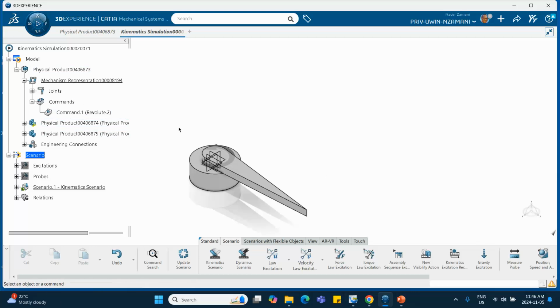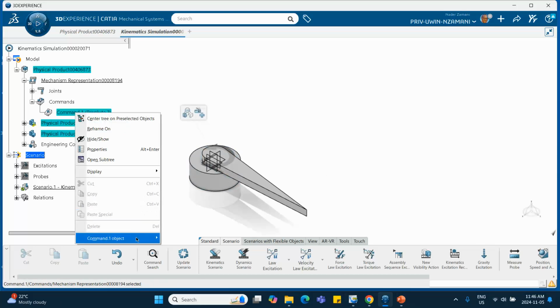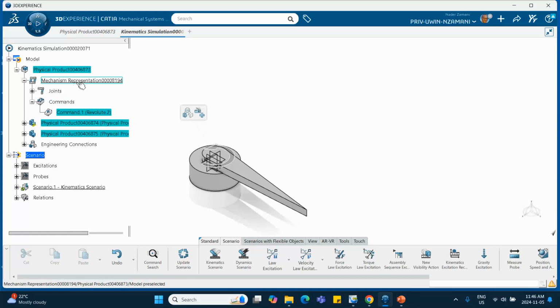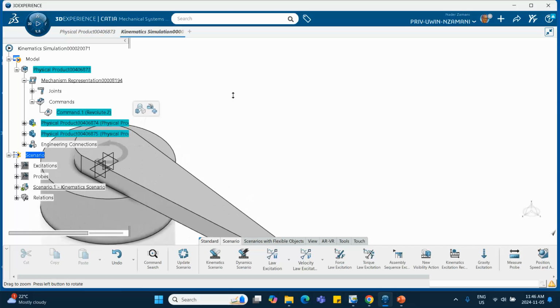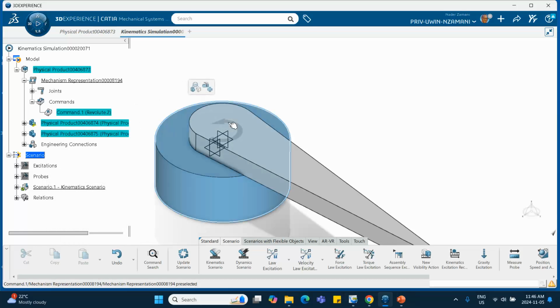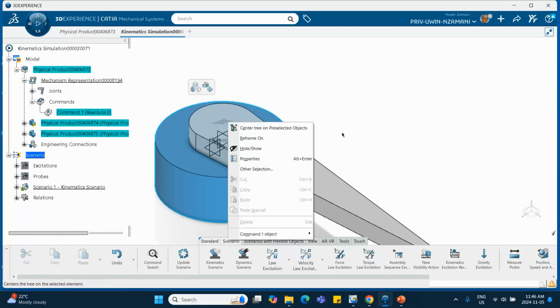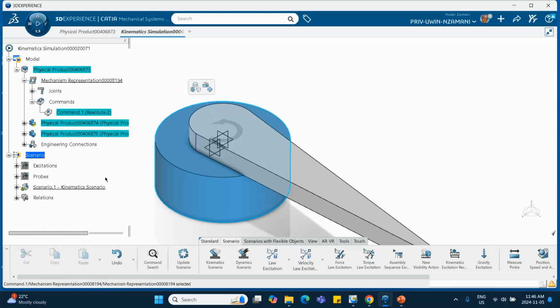Now, can I flip this direction? No, see, it won't let me flip the direction. So if you want to flip the direction here, what I need to do is put a minus sign in front of that formula. Ordinarily, I should be able to take this thing and flip it, but I don't see it here. It doesn't let me do that, but that's okay.